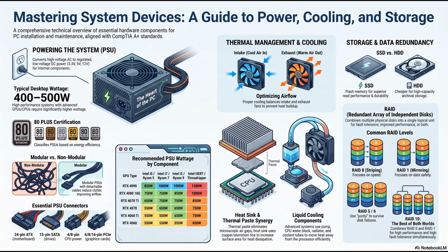These come in 6-pin, 8-pin, or the massive new 16-pin variants. These exist for one primary reason: to feed your graphics processing unit, the GPU. Modern high-end graphics cards are practically supercomputers unto themselves. Which they really are. They have billions of transistors and their own dedicated banks of memory. While the motherboard slot can provide a baseline 75 watts, a top-tier GPU might demand 450 to 600 watts all on its own. But why do they need a special 16-pin cable for that?